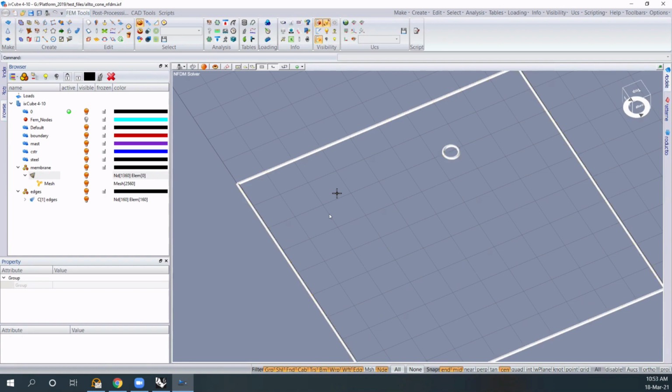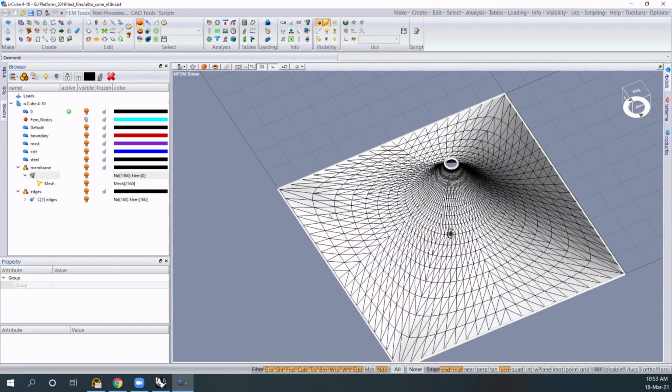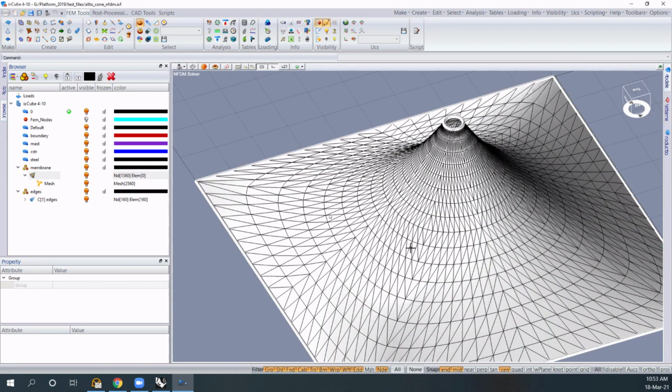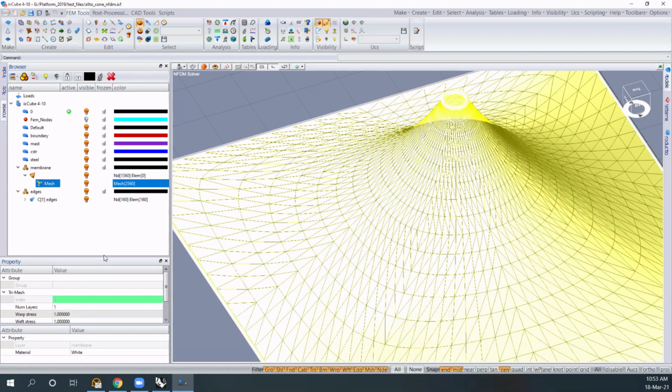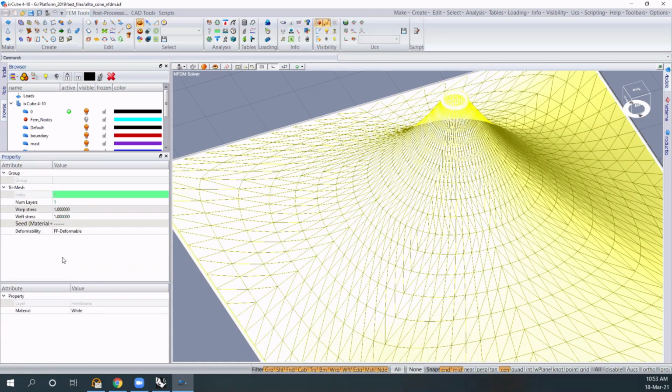Okay. We are not using the first density method. We are using the natural force density method. I unhide my mesh. Now my mesh, this mesh here, is the soap film. If I double click on the mesh, oh, I have to activate my filter. If I double click on the mesh now, you see that now we see properties on the mesh.